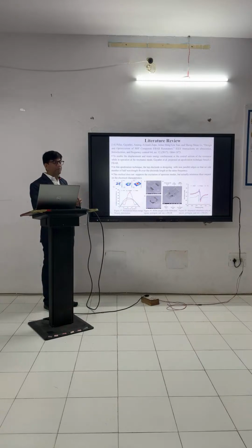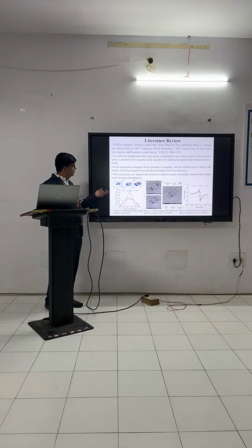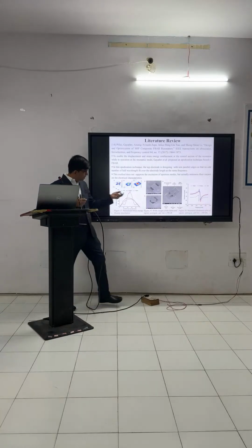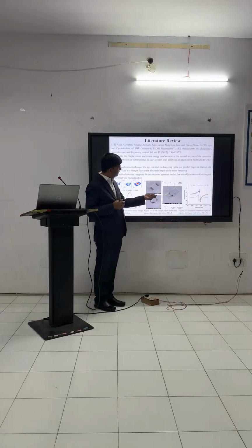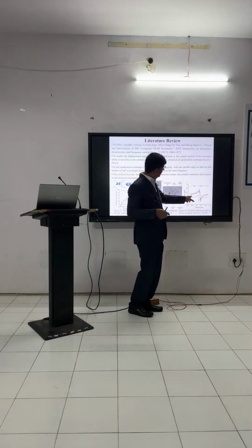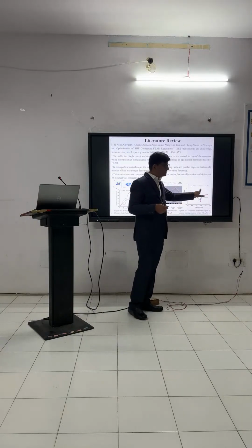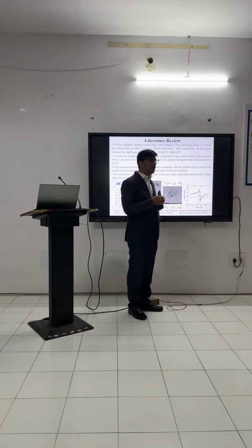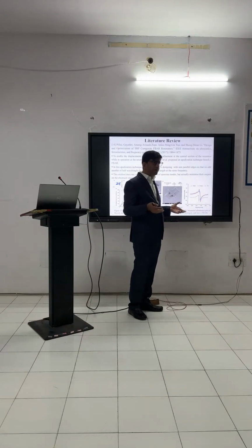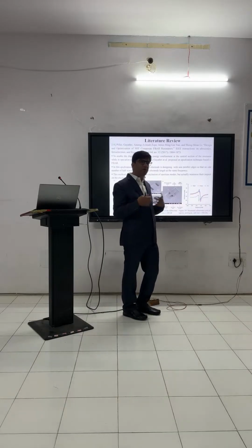Then we have different methods of optimization because, see, this device looks very simple, but understanding how it will be optimal is hard. There are so many problems, such as generation of higher harmonic modes and spurious modes in your resonance. So how can you avoid them? You can change the structure of your top electrode, and with the help of that you can improve your acoustic response, because we have so many spurious modes. If we want to design a filter, we want a clean response without spurious or higher harmonic modes. So for that purpose we need to optimize. How can you optimize this device?